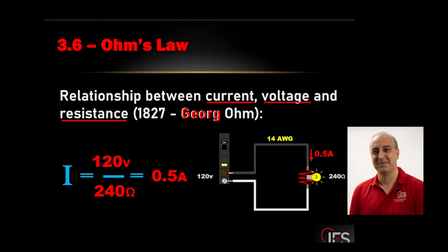So yeah, what you have to do here is, 14 gauge is good, but we got to change our receptacle to a 15 amp receptacle, and that will protect the wire. So anytime you try to pull more electrons here than 15 amps of current, boom, this one stops it. It's like, no, no, no. So it could be a short circuit. Remember short circuit where there's no big resistance? You connect the hot and neutral together. It'll try to draw more current and it'll trip the breaker.